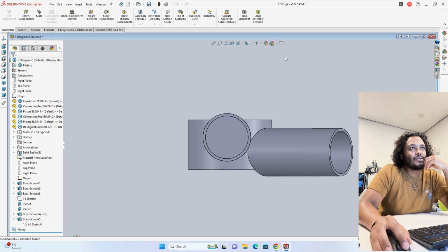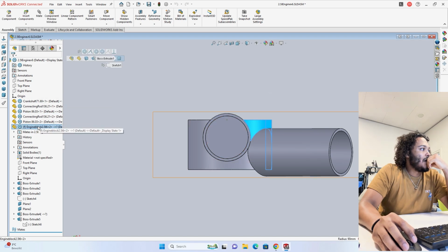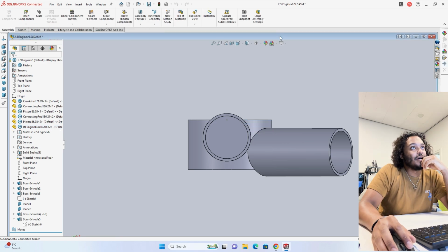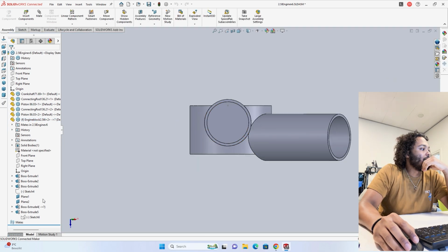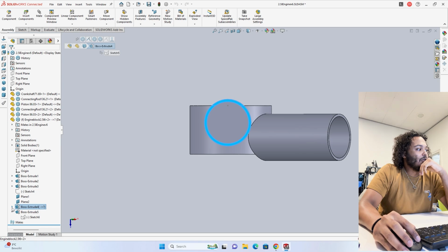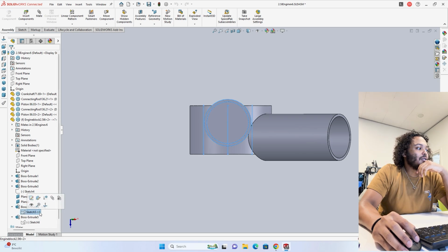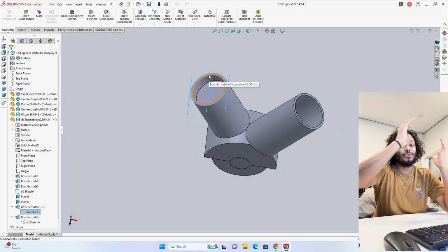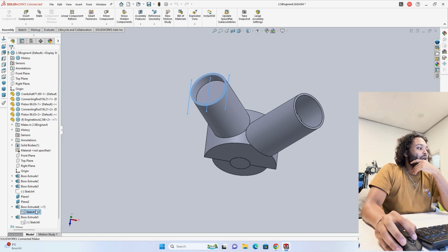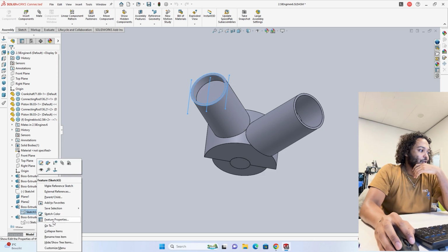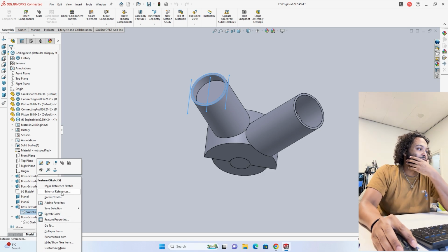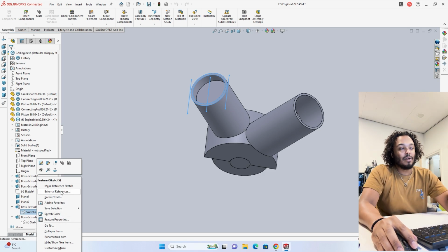Or is it the engine block itself? I think it's the engine block itself that has the references. Yes, I think it is. So we can go into the engine block. The piston, I think, is free from references, but you can see here that on this actual sketch there is a question mark behind it, which means it's using dimensions from another component in order to build this. You can just make sure to break that reference so that you can still modify it, but it maintains the same dimensions.